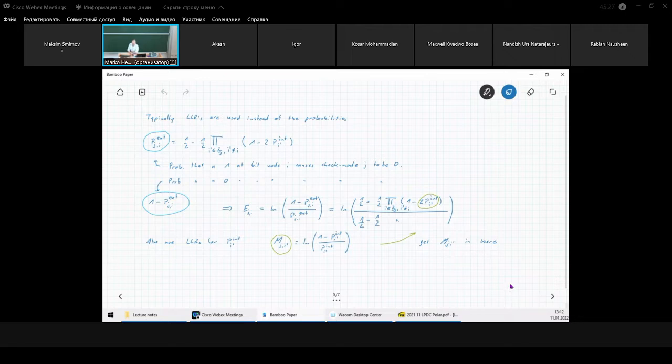So from the understanding point of view, this is clear. Just in practical systems, it's done slightly differently. So far, we talked about probabilities. This is maybe easier to imagine, easier to understand. In the next step, we move again from probabilities to log likelihood ratios, which just makes the equations a bit more difficult. But you see, instead of talking about these probabilities here, we can also talk about log likelihood ratios, just setting these probabilities in relationship and using the ln.